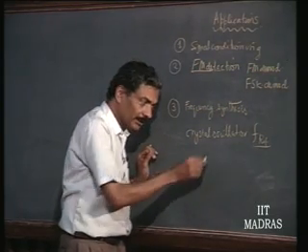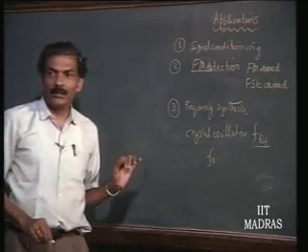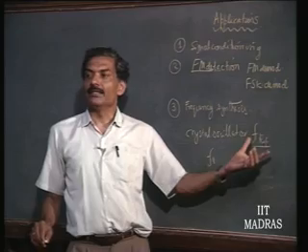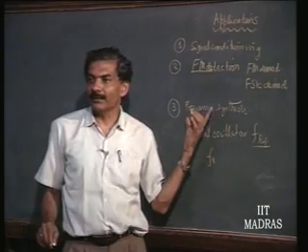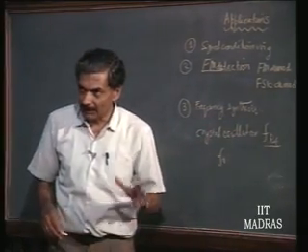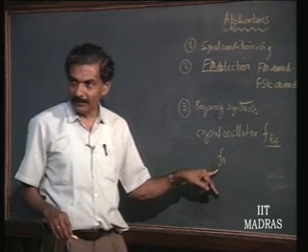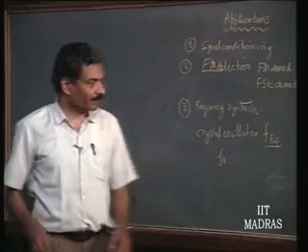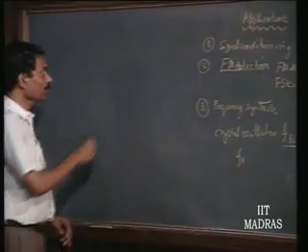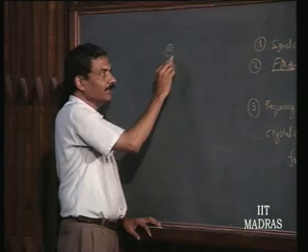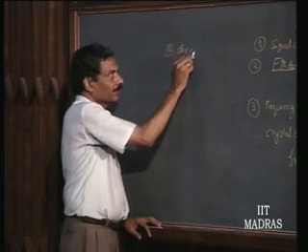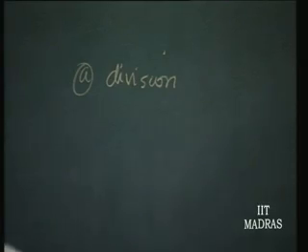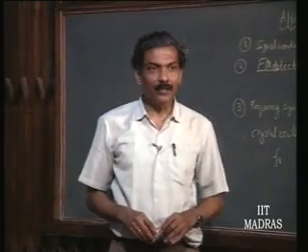How to synthesize output frequency of any value using a given reference is the purpose behind frequency synthesis. Okay. The problem is how to get F naught of any value giving F reference as the input, that is frequency. Now, one or two operations that are needed for this straight away. One is division, frequency division. This division is the simplest operation performed. Okay. How?